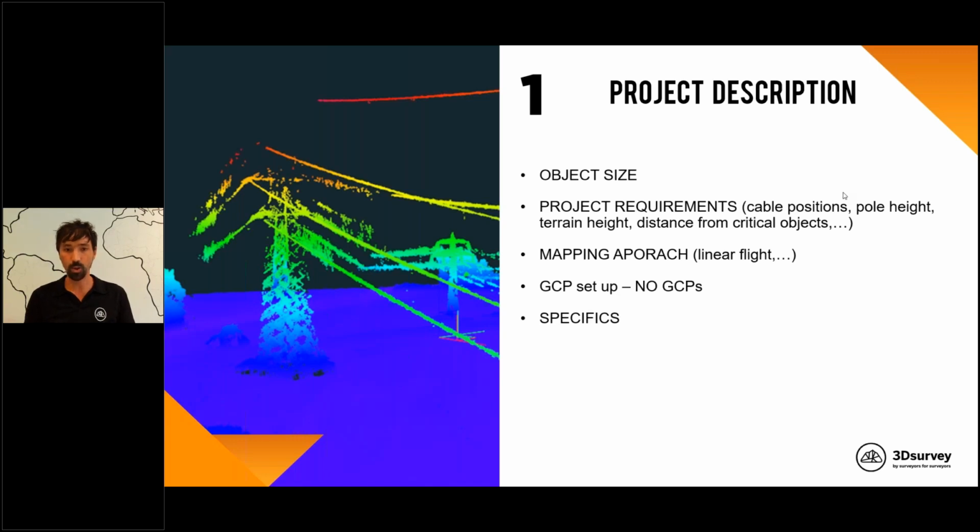and it's easier to reconstruct the points later also. Okay, so our suggestion, as you will see later, is if you have power poles of 40 meters, fly at 100 meters. If you have higher ones, fly at 120, 140 meters, and set the camera a bit to the front. I used the 60-degree gimbal, and it gives me great results. So 90 degrees is fully down, 0 degrees is horizontal view, and 60 degrees is a bit in front. You will see it later also in the software.